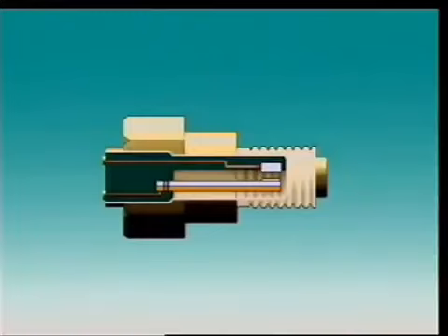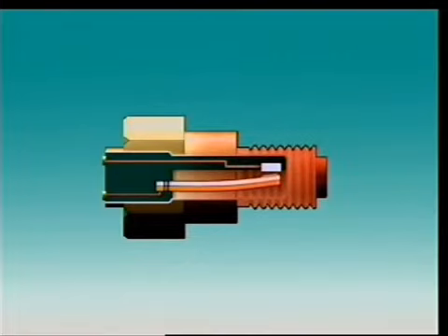Heat switches can operate on the bimetallic strip principle. It consists of two different metals or alloys attached back to back. As different metals and alloys heat and cool, they expand and contract differently. That means that if they are joined and then heated, the faster expansion of one will force the whole strip into a curved shape.